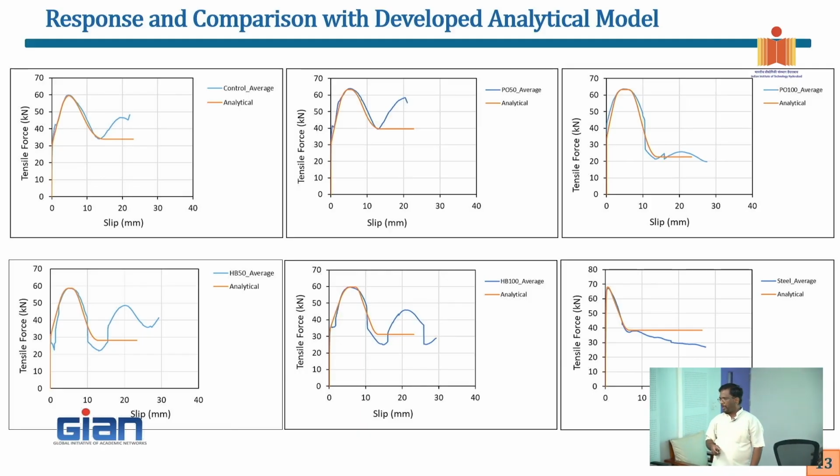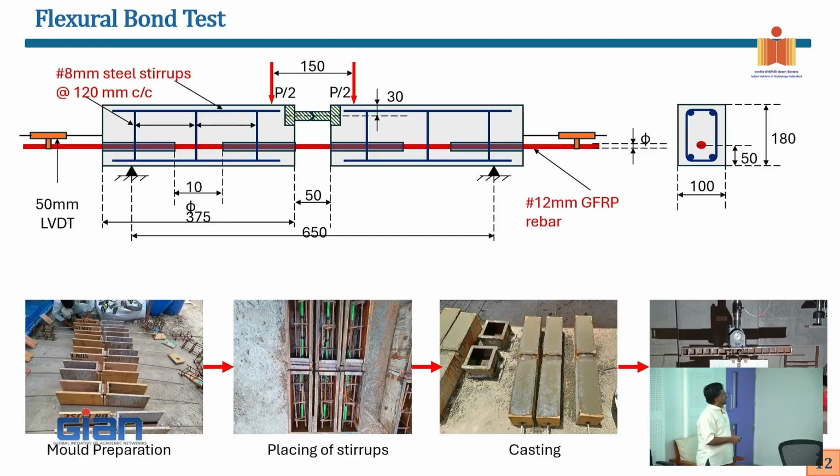Okay, so you see here, this is the setup, right? This is the bonded length, 10 times the diameter, here and here. When I push it, you will have compression, right? So there is going to be a bending moment here. The compression will be developed in this hinge that we put in here, and the equivalent tension will be developed on the bar.